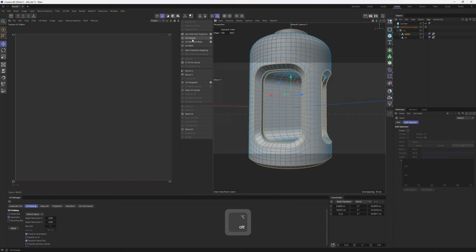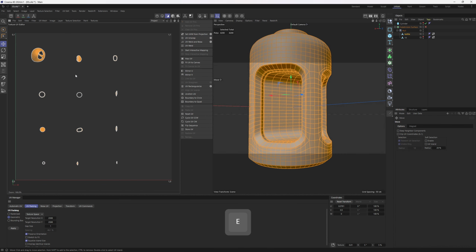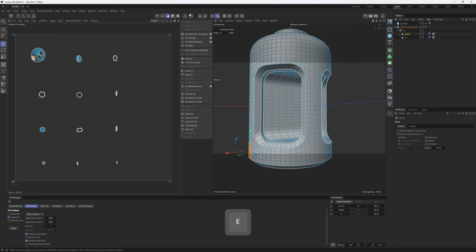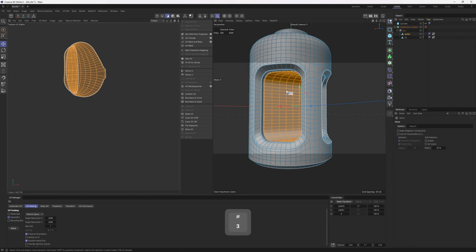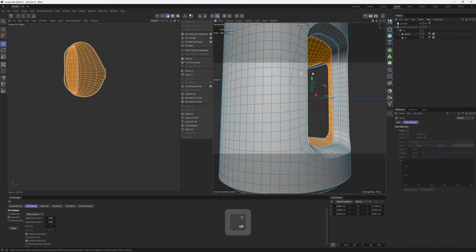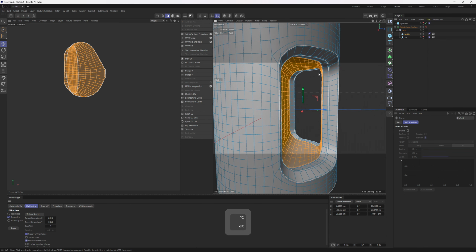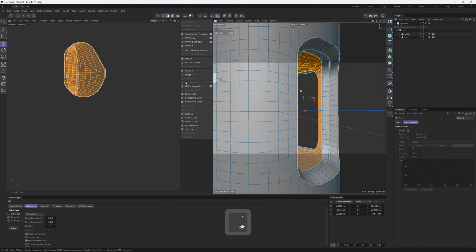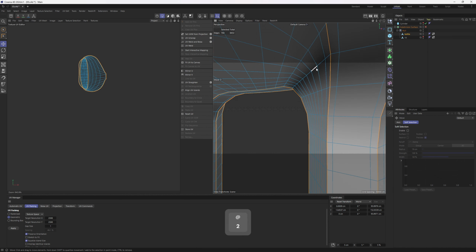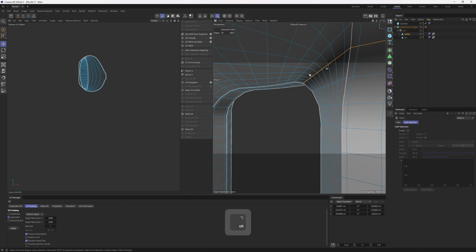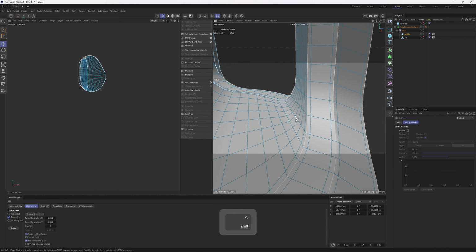Next up, let's click on UV Unwrap. I just want to split these UVs into different parts so that it's going to be easier to work on them. Some of them will look really weird, like this one. The reason is that polygon island or UV island doesn't have a seam, doesn't have an exit point. I will just come over here and select these edges. You usually want to select the least visible parts as seams.